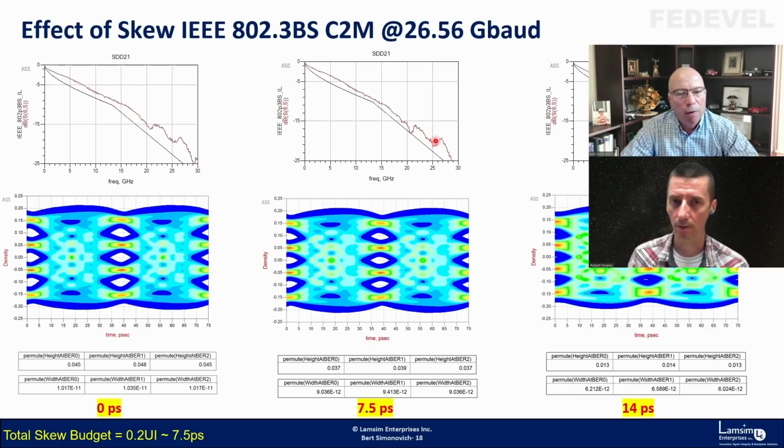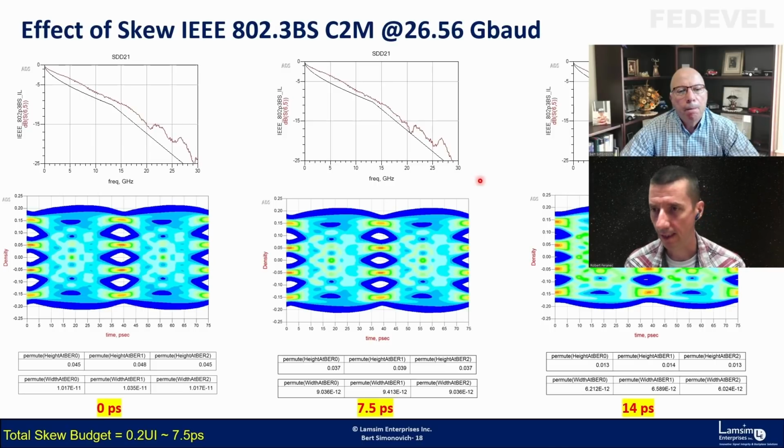Okay, and then from this measurement, you will get this red graph. Yes, exactly. That'll be the loss of your channel. And the red graph is also telling you basically where the resonances are. For example, in the first one, there is like 20 something gigahertz. Yeah, they're not deep, right? Mm-hmm. They're just little discontinuities affecting it. And that's why they have this limit line showing, they're accounting for things like that. So any resonance or any dips should be above that line for the channel. And that's part of this 802.3 specification.